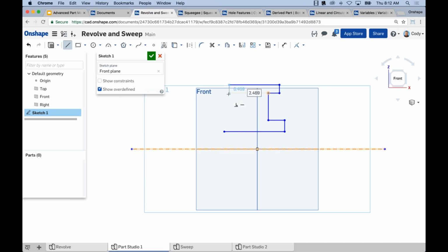All right, so a few tips that I have. This is a general sketch tip, but you'll notice there will be times when you want to create some kind of a reference to something that's not popping up automatically. An example, I'm drawing this vertical line. I want it to be the same exact length as the line to the right of it. But as you can see, as I move this, I'm not getting that reference to the point on the right.